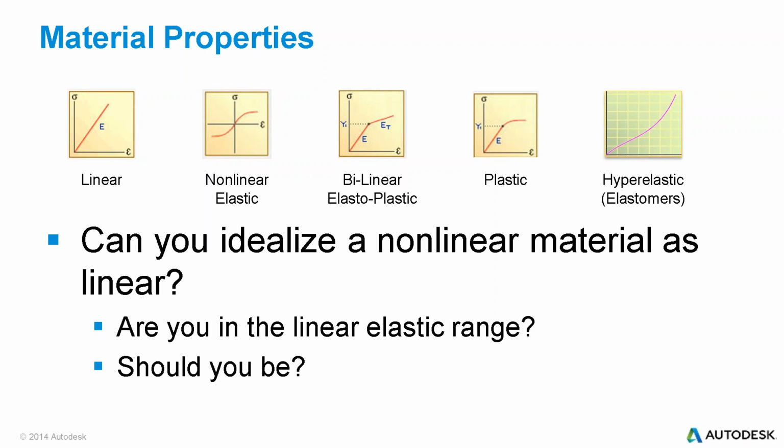Then you get into a small window where it becomes nonlinear. Same thing goes for plastic. There's a very finite window where plastic behaves like a linear material. Then all of a sudden it explodes into a nonlinear graph. So depending on the material you're working with, you've got different options of what material type and the behavior of that material. Nastran can adjust for all of those.